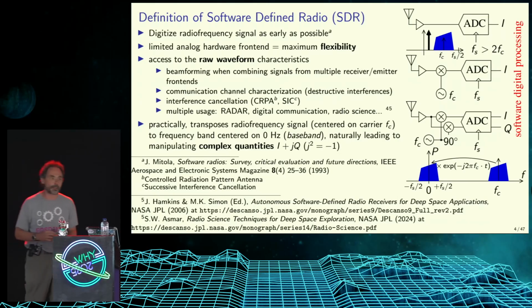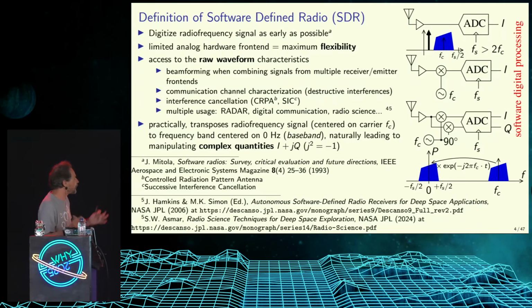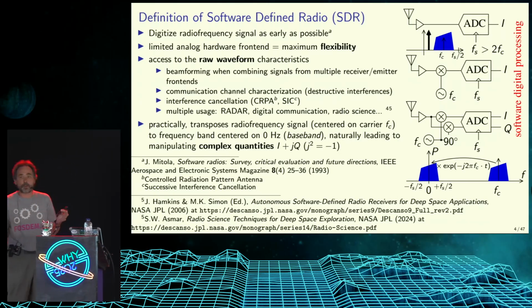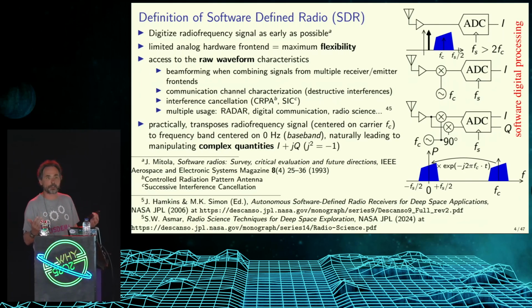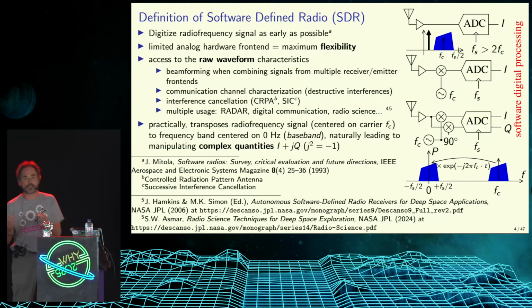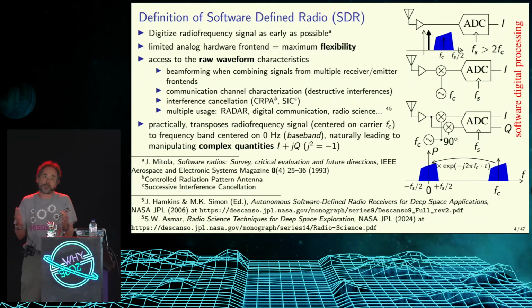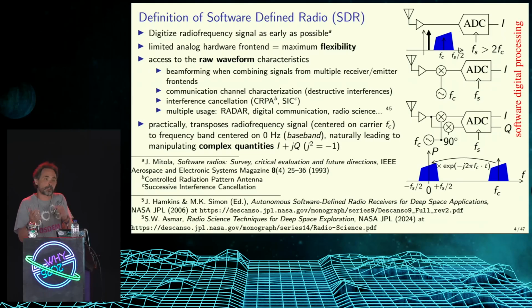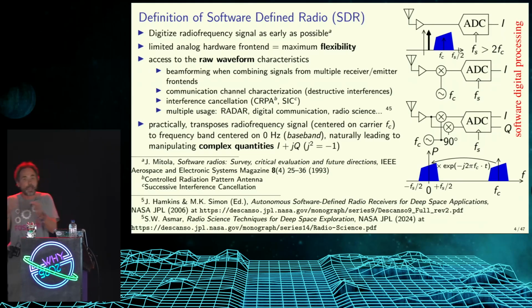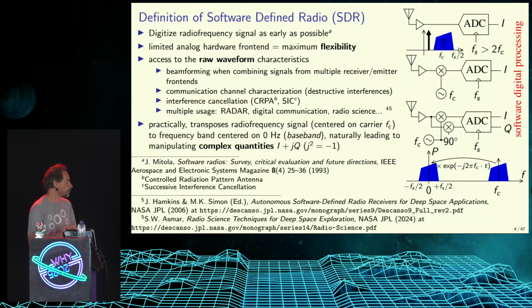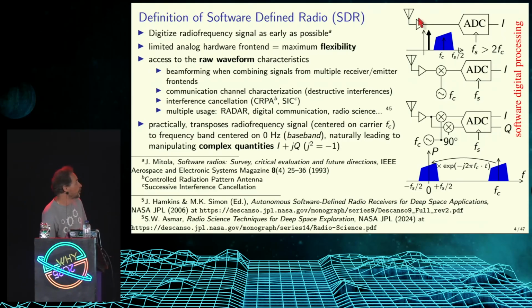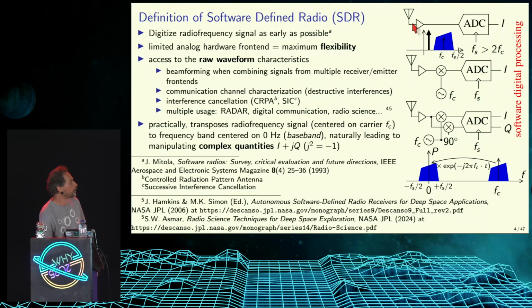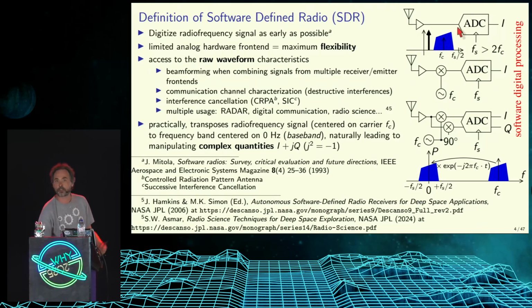Now, software-defined radio. If you're not familiar with software-defined radio, the objective of SDR is to try to minimize as much as possible the analog radio frequency front end and move all the processing to software. And that's so much fun because it mixes my two interests, physics and radio frequency engineering, and computer science, high-performance computer science. The ideal software-defined radio would be to connect the antenna, maybe amplify a little bit the signal to an A to D, analog to digital converter, and this stream of data would be